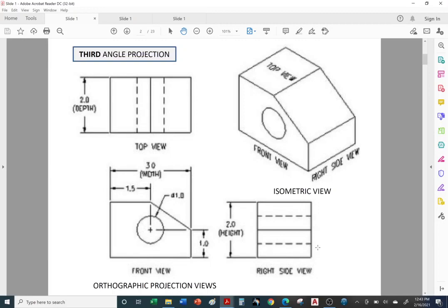If you ever have a solid line overlapping a hidden line on one of your views, the solid line wins because we can actually see it, and we actually draw the object lines thicker than the hidden lines. We'll talk more about the alphabet of lines, the line types, and the line thicknesses.